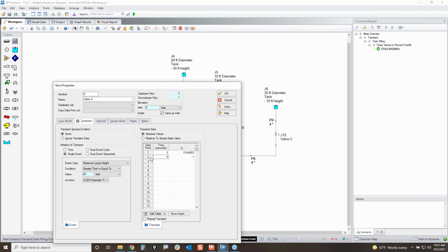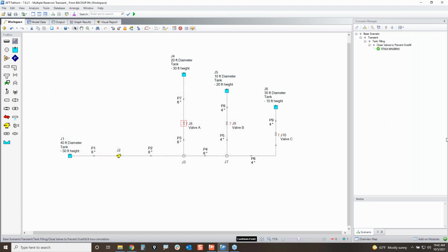So that's where we need to do a waterhammer analysis so we can capture the rapid propagation of pressure waves throughout the system. So in Impulse, I'm actually going to be doing a number of different scenarios. My first scenario is going to be modeling all of these valves being open, and I want to see what happens when the first valve closes.